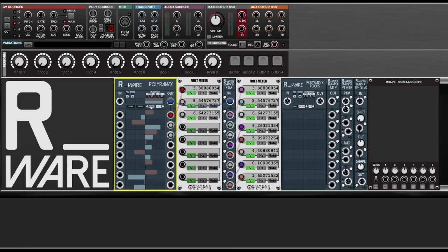We can lock the attenuators, and now if I drag over the bar, only the DC offsets are manipulated, but the attenuators stay the same. This applies also to randomization and reset. I can do the same for the DC. Now only the attenuators are being manipulated because the DC is locked. If I lock both, well, I can do nothing because now everything is locked.